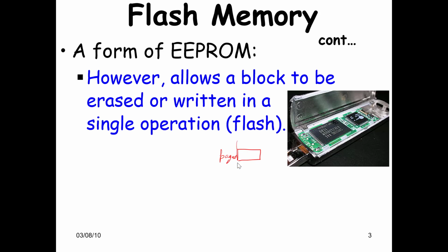So then what you have to do is you have to take a block of pages. So it's known as a block. The entire block has to be erased in the sense that the entire block you'll sort of have to fill it with all zeros and then rewrite the entire thing. So what is done is whatever is semi-written, that is transferred to a new empty block. This block is erased, and then there is a transfer back, or let's say in a new empty block, whatever page you wanted to write to, you put in the modifications and you write to that page. So this is what makes writing a rather slow operation in the case of flash memory.